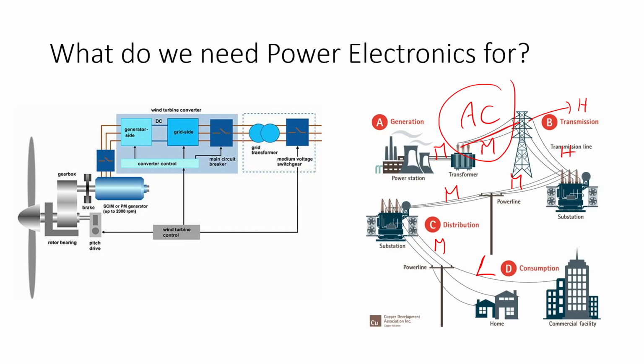So you need certain power electronics to convert in many ways. Actually, first convert to DC, and then in an inverter convert DC to AC that has the same frequency as the grid. So you can see here several power electronics devices inside. Okay? And so you hear the term inverter that converts from DC to AC, and you need the frequency of the output from the inverter to be the same as that of the grid. So it needs a kind of control. If not, without control, maybe you get a random frequency which does not match the frequency of the grid.